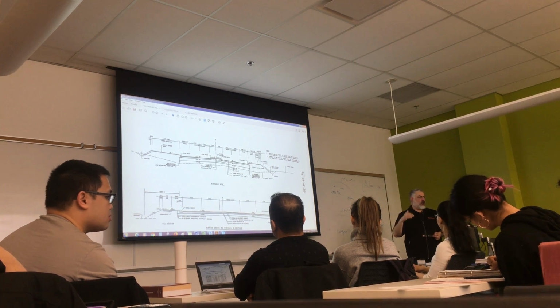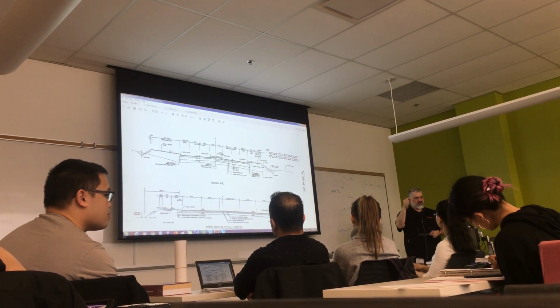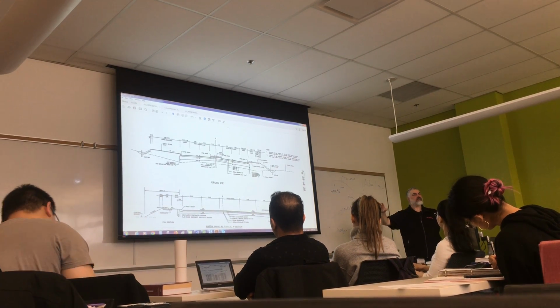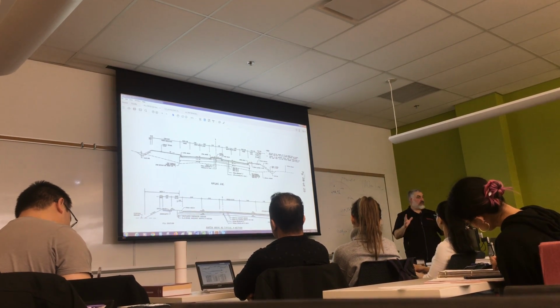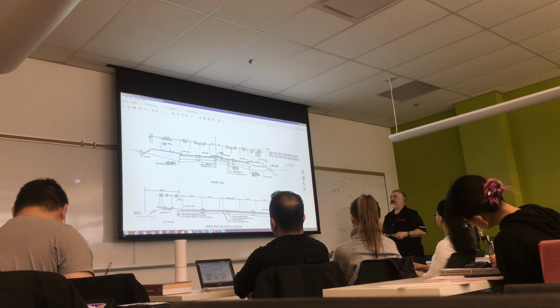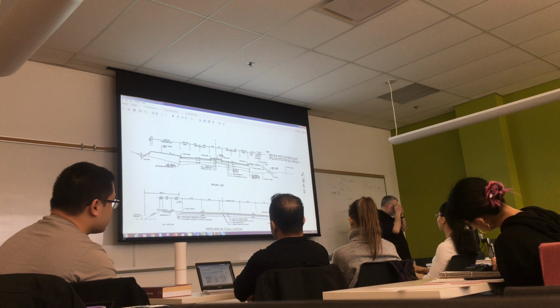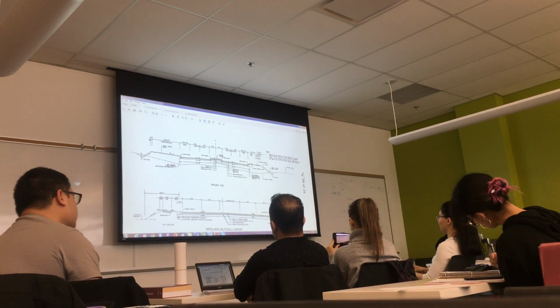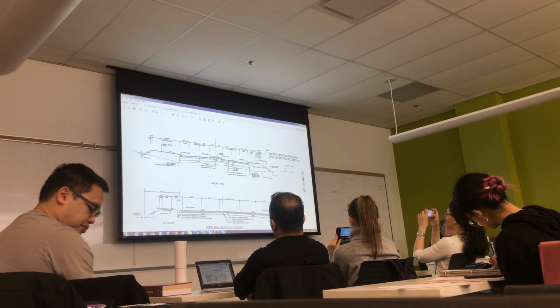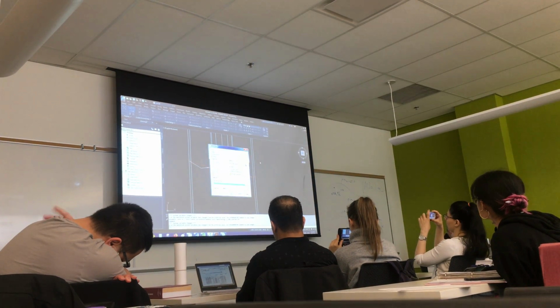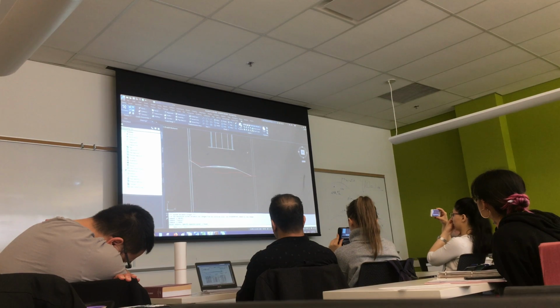So the methodology, I hope, is clear. Existing, proposed center, widths, depths, and then analyze each side. Draw your fill or cut. You're going to have one of each, I promise. And then annotate it with everything you need. Now, to plot this, because you drew everything at 1 to 1 meter, once it's all annotated, let me just get rid of this.